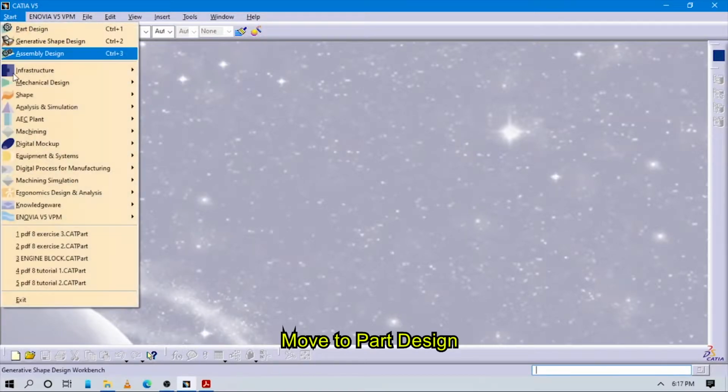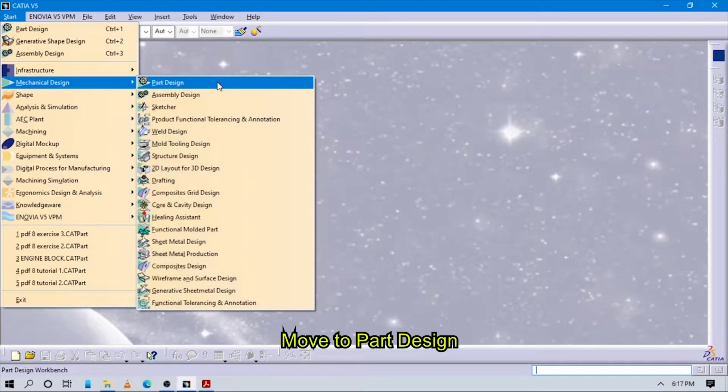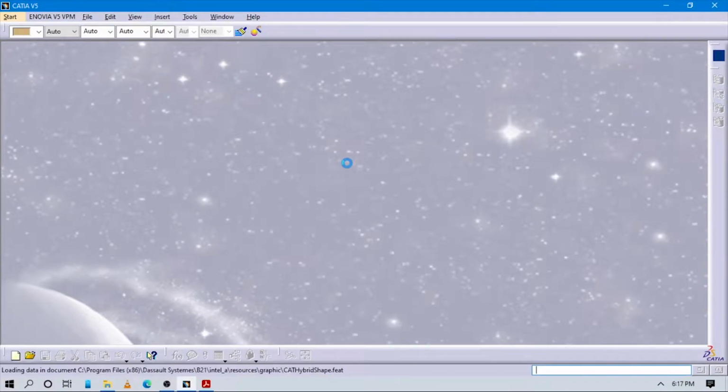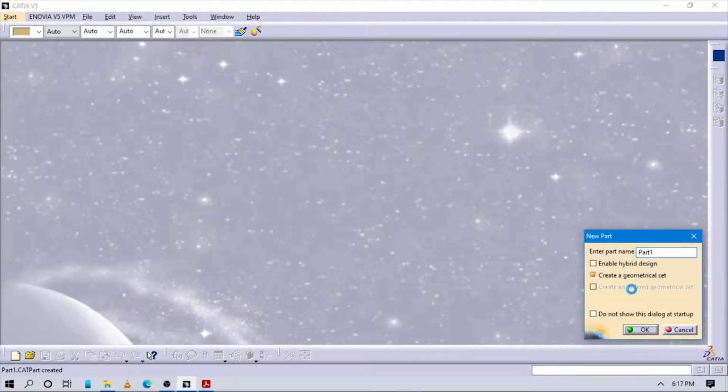So first of all, open Catia, go to start, mechanical design and part design, and give whatever name you want.